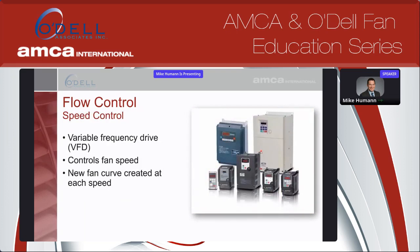And the last flow control is speed control. This has obviously become a lot more common in the industry because of the flexibility of it and the power savings you can get from this. So you can get a lot of energy consumption savings here. It controls the speed of the fan by changing the frequency that the motor actually sees. Motors do need to be designed to handle these, and in some cases with larger fans, we do actually make fan modifications as well to handle these.